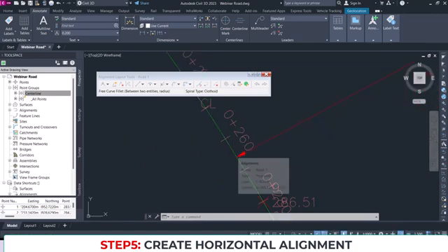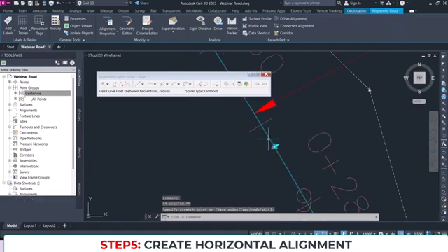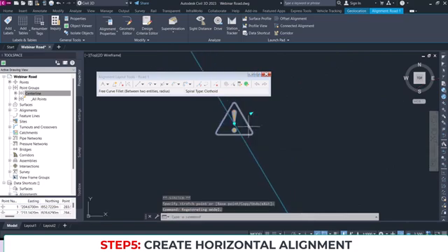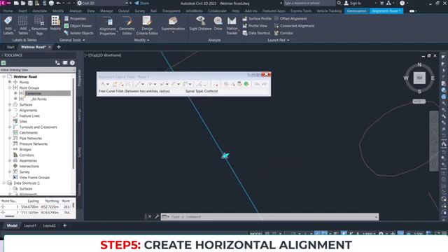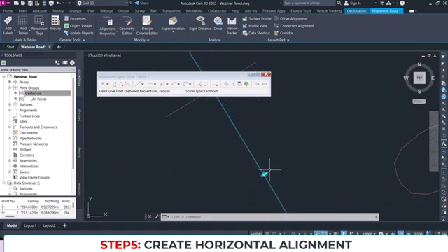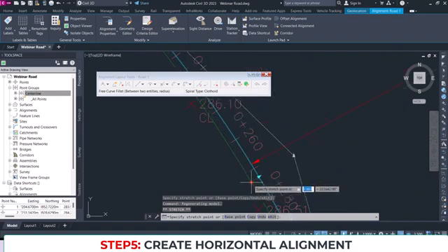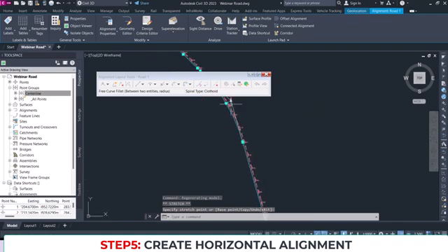Let me just make it below and then show you how it will show an error. Let's say we push it upward here. Can you see there is a warning sign here? What does that warning sign say? Minimum radius is violated. The current radius is 344 and the minimum radius should be 437. So we have to move it back in order for that warning symbol to go, and our road is correctly designed. Okay, so now we are back to 488 somehow.